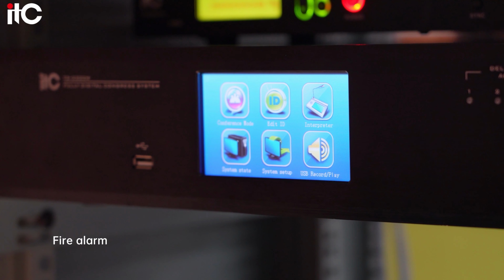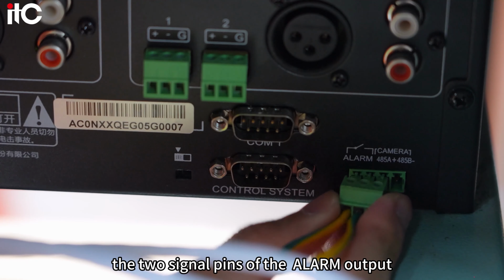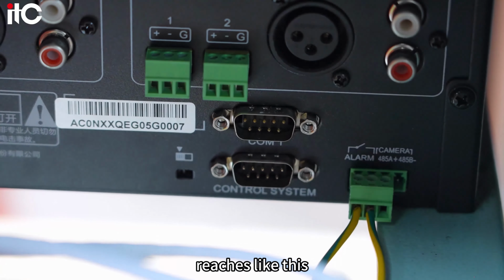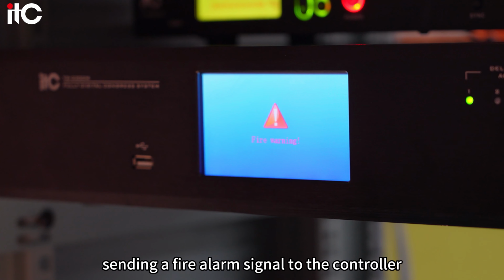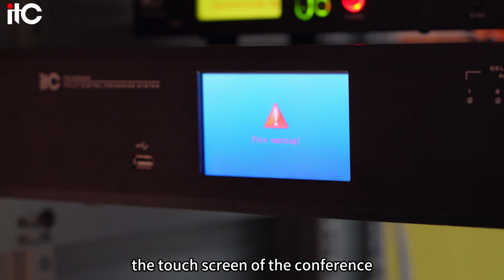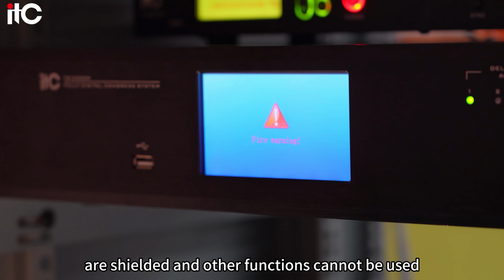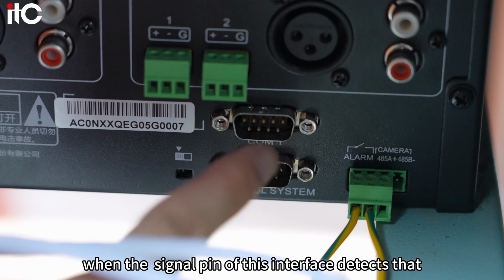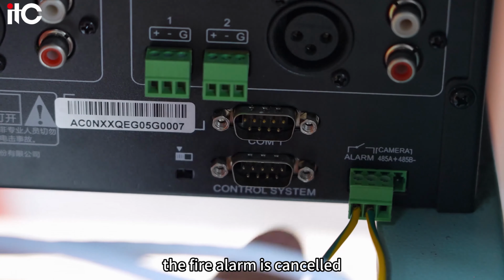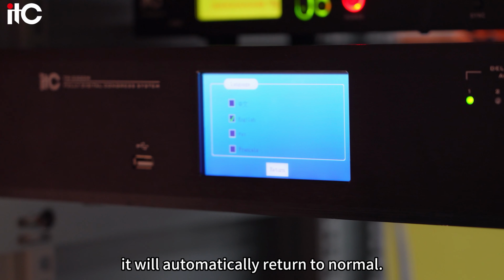So for the fire alarm, by short circuiting the 2 signal pins of the alarm output, which is like this, on the back of the conference controller, you simulate sending a fire alarm signal to the controller. The touch screen of the conference controller and the unit devices are shielded, and other functions cannot be used. When the signal pin of this interface detects that the fire alarm is cancelled, the circuit is opened. It will automatically return to normal.